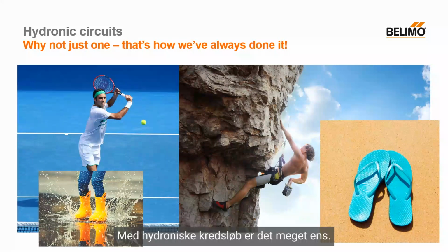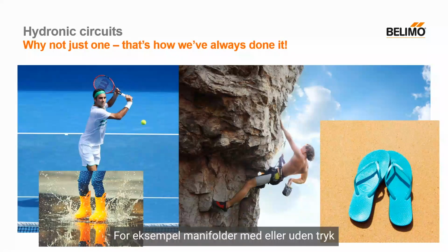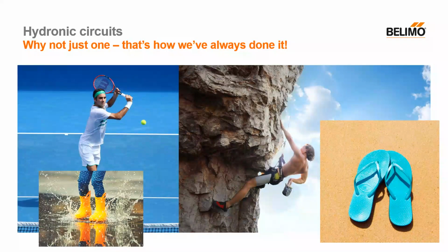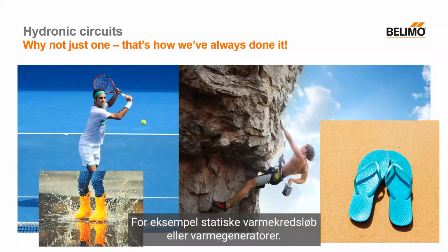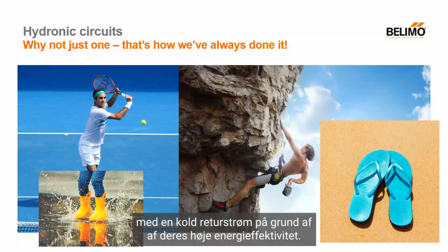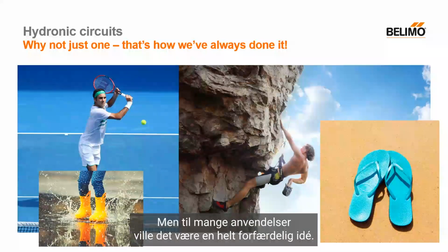With hydronic circuits it is very similar. There are different requirements, for example, pressurized or pressureless manifolds. Consumers that are operated with varying inlet temperature, depending on the exterior temperature, for example static heating circuits. Or heat generators, for example condensing boilers, which should be operated with a cold return flow, on account of their high energy efficiency. By now it should be clear. You could always use the same hydronic circuit. But for many applications this would be an absolutely terrible idea.